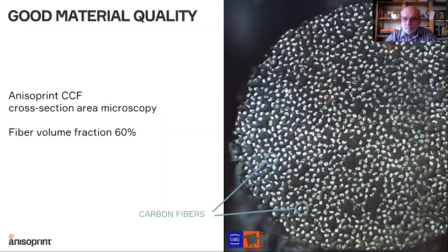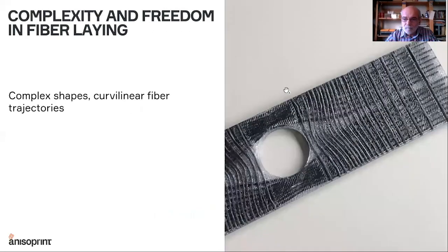So that's a very high quality material, and the adhesion between fibers and polymer is very good, because most of the reinforcing fibers have a special sizing for thermosets. To achieve good adhesion of fiber to thermoplastic, you normally need to either remove this sizing or apply some special sizing. But in this case, it's as simple as it is, and you get very high quality composite fiber.